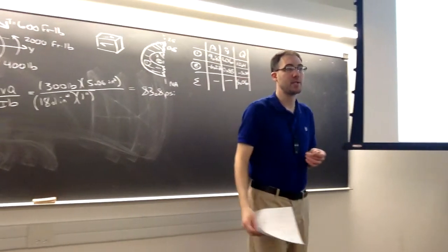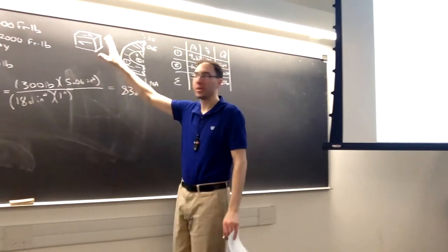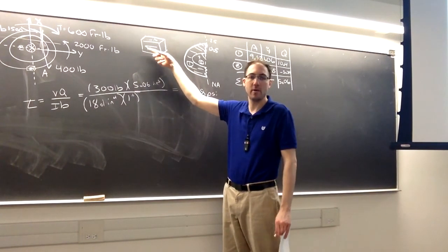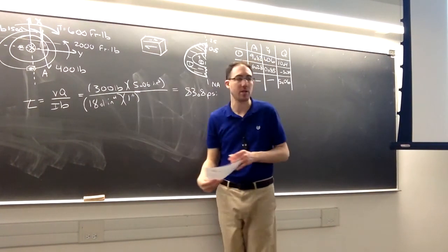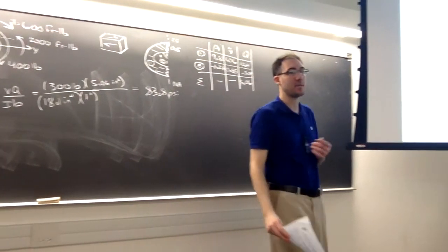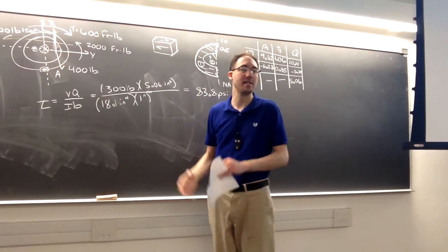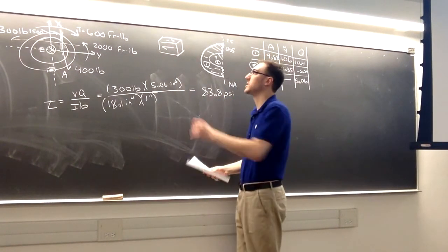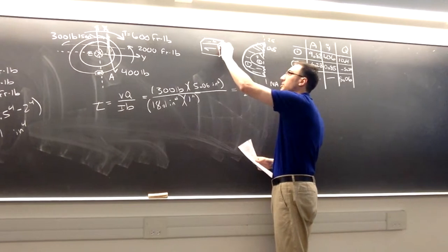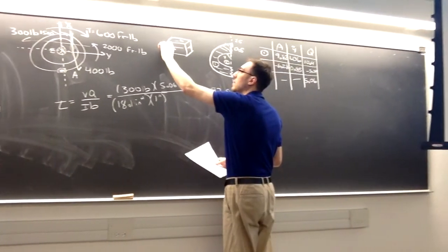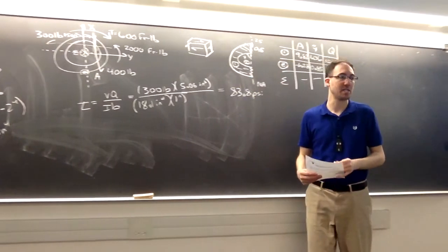But what happens to my stress cube? Because it's so small, you can think of it as a force here. If I have a force on the front face going to the left and a force on the back face going to the right, what is going to happen to my cube? Right, it's going to spin, which means it's not in equilibrium. So to balance out that spinning, I also get a shear stress on the side face that's going to counteract that spinning.